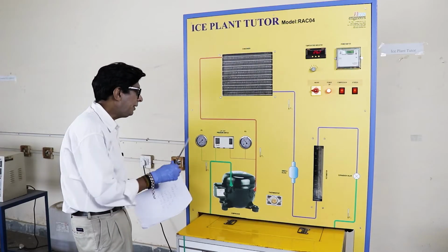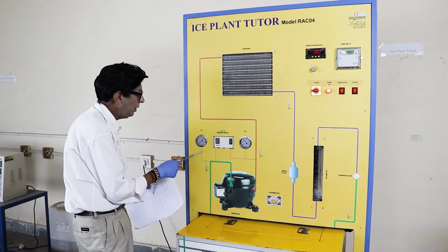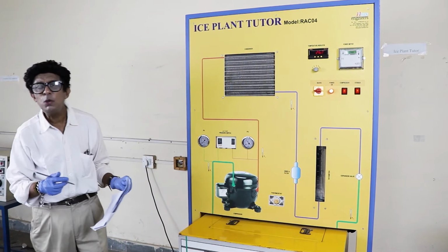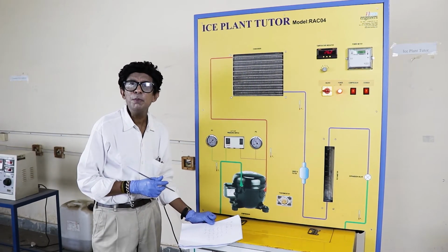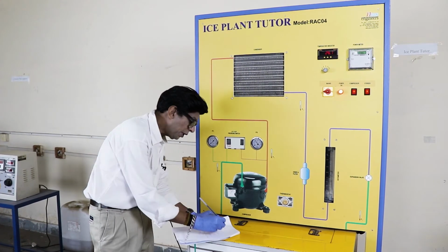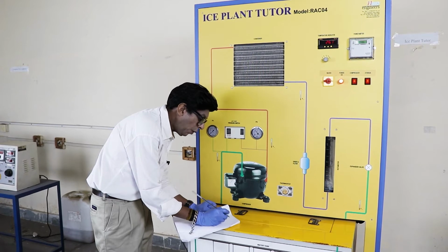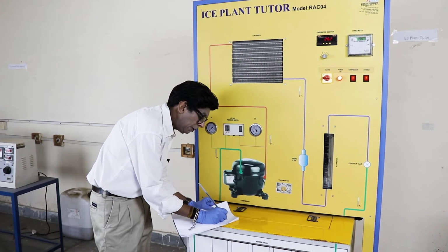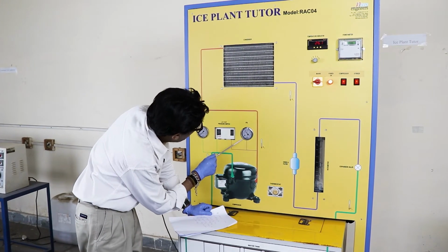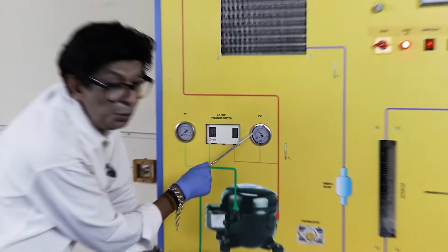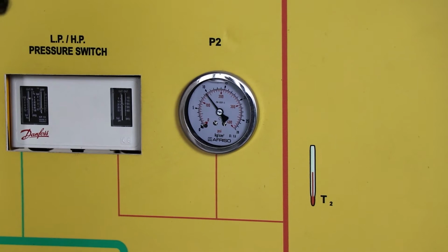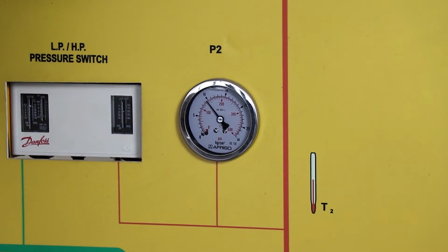So first of all, we take the pressure at the suction of the compressor, which is P1, and the gauge is showing 0. Actually, this is not 0. This is atmospheric pressure, because gauge pressure 0 means it is at atmosphere. So you can consider it as 1.01 bar, the inlet pressure here. The outlet pressure of the compressor is about 10. The unit is kilogram force per centimeter square. So I put this as 10 kilogram force per centimeter square.